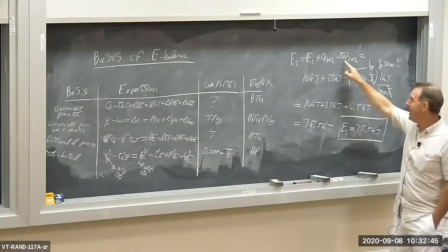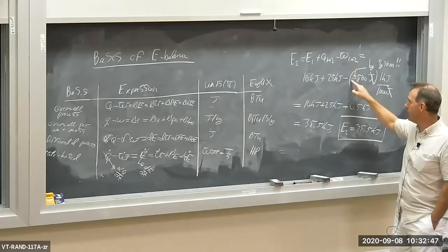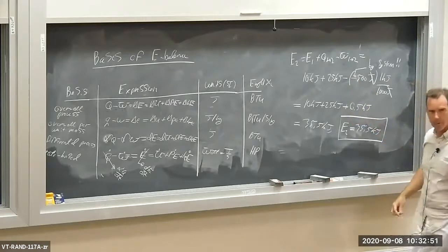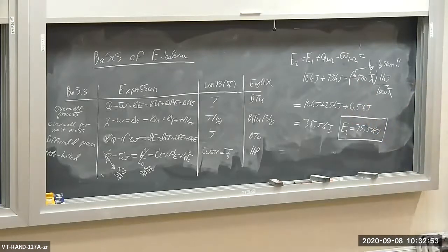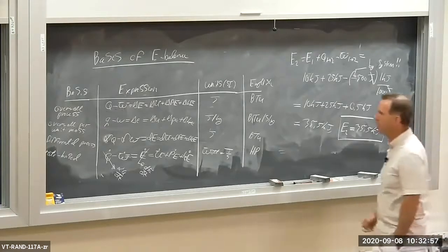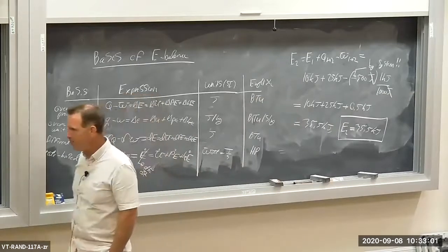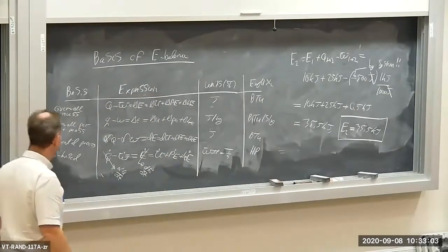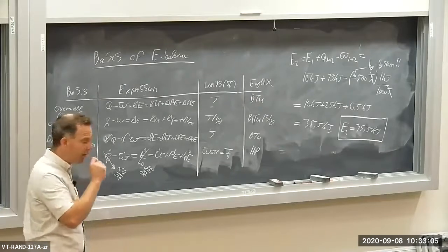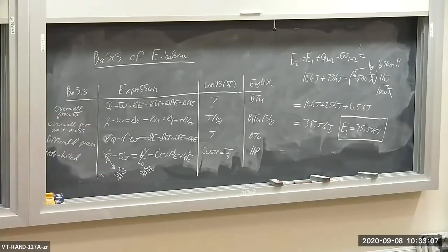So I had to put a negative sign in front of the numerical value. It canceled out, and that's where the positive sign came from in front of the work term, okay? So you got to make sure you understand work in the energy balance is work by the system, okay? It's positive when it's by the system. Let's do another example here. Take a pause for a moment so I can get it set up.